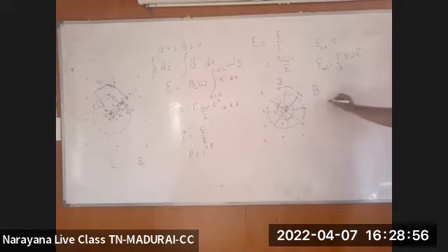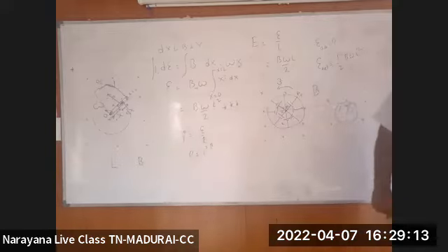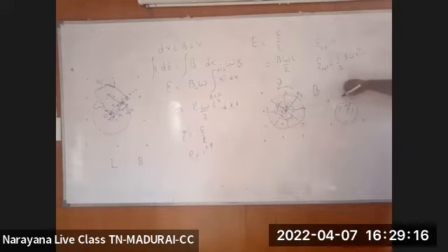So in the disk case also, same magnetic field, with highly densely packed spokes, it will constitute one disk. With the disk of radius, let's say, r meters, it is rotating with some angular velocity omega in the magnetic field.